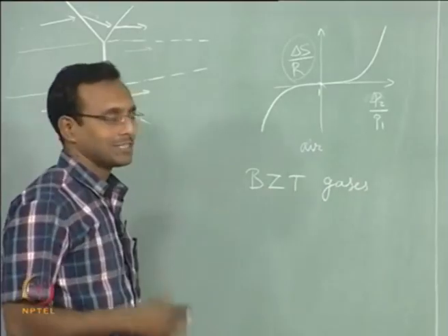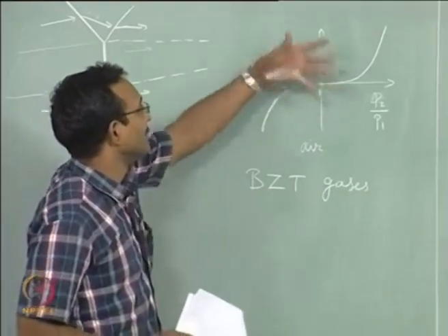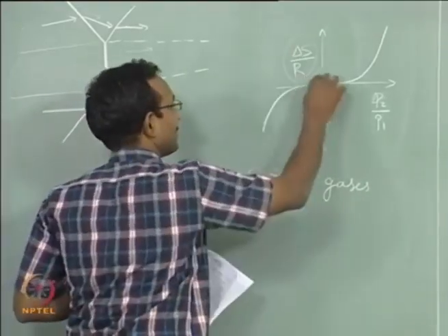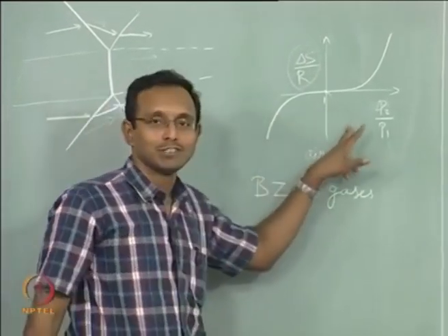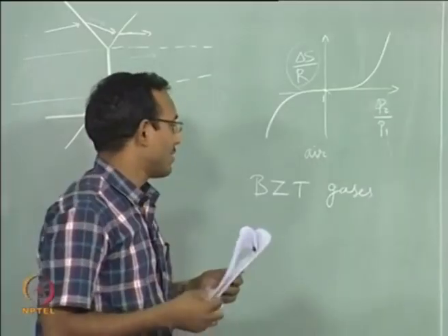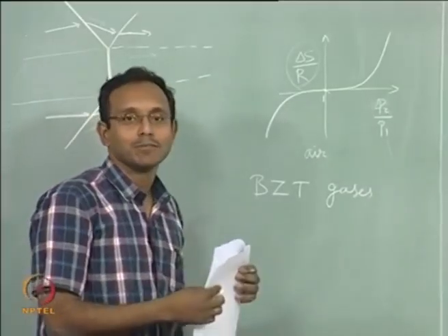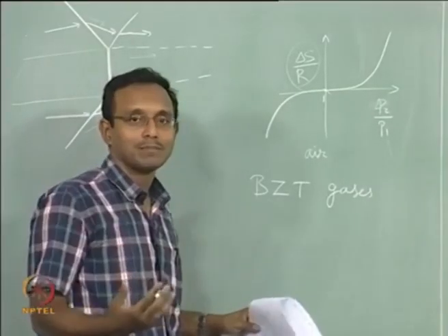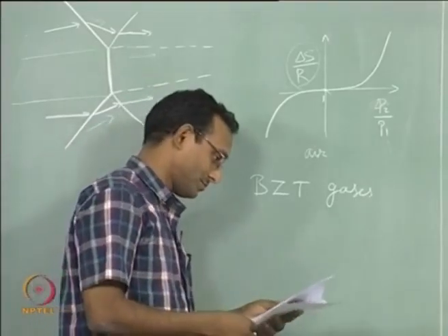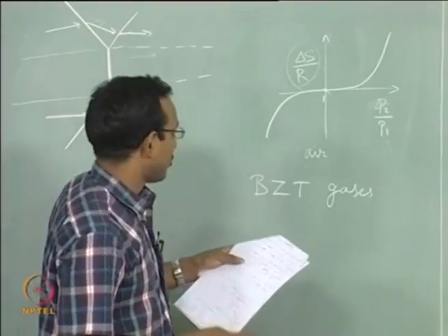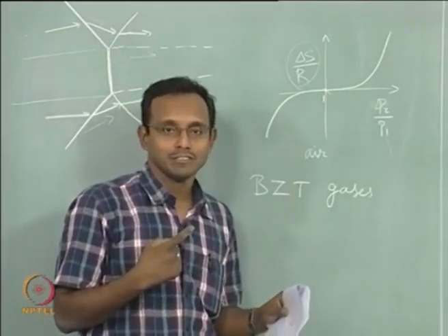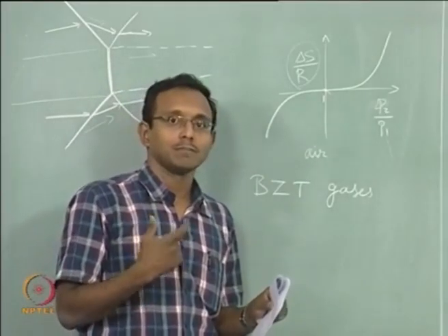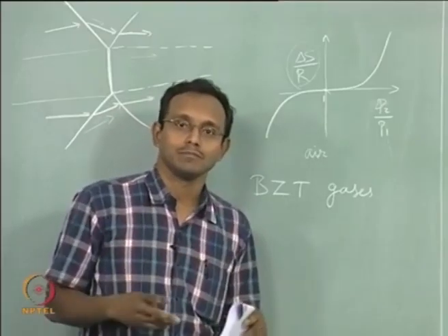This special gas will have this curve inverted, that is, it will go the other way, where only expansion shocks are possible, compression shocks are not possible. But most common gases do not have this property. So we will not talk about it in our simple gas dynamics world. So that caution being given, now I know one extra statement from before, which is expansion shocks are not possible.